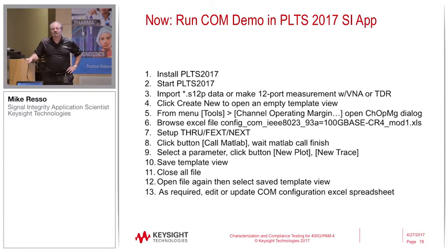Yeah, so, yes. Oh, this is really good input. This is the first time I'm hearing this. So the total number of ports that you've read in the latest standard is how many differential channels? If you are considering 100 gig CR4 or KR4, then it's 4 TXs and 4 RXs. If you go to 200 gig, 400 gig, then depending on whether it's by 8 or by 4, it changes. Okay, so there's your answer. So it's going up from 12. Yeah. Thank you.